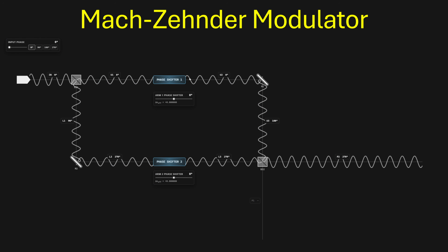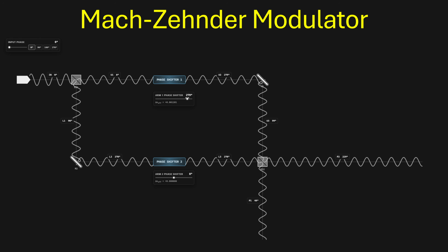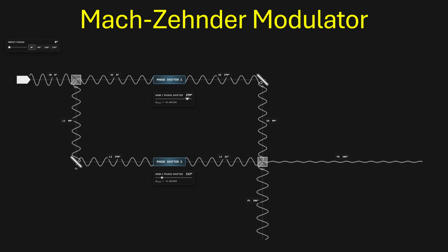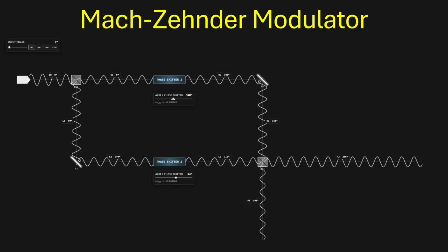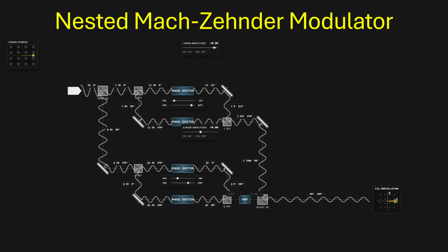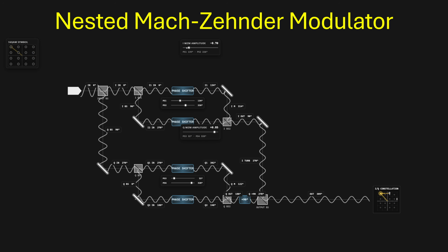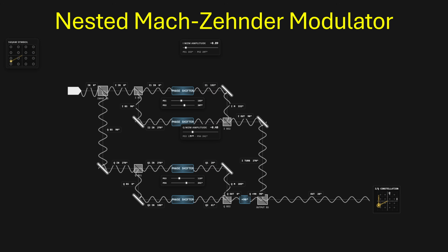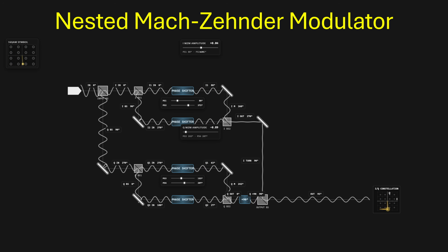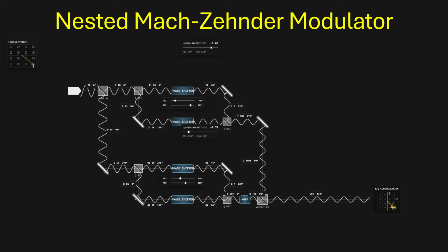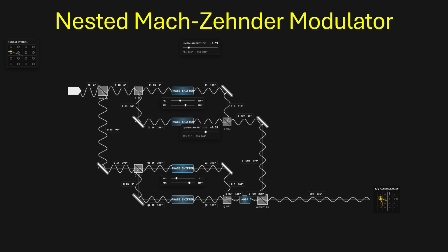In a Mach-Zehnder modulator, phase modulators are placed along each arm. If only one arm is phase shifted, both the phase and amplitude of the output path will change. By moving the phase shifters together, we can change only phase. Likewise, by moving the phase shifters in opposite directions, we can change only amplitude. To produce arbitrary phase and amplitude combinations for QAM, this requires a nested Mach-Zehnder modulator. This uses 2 90-degree phase-shifted MZMs that will modulate only the amplitude of the I and Q channels. These more advanced IQ detectors and modulators are common for long-distance high data rate lines like undersea cables.